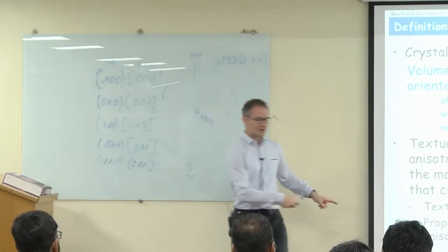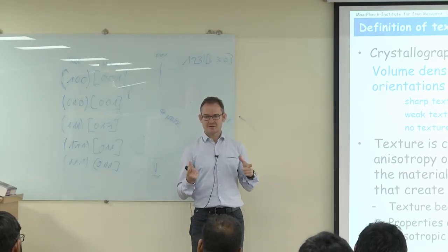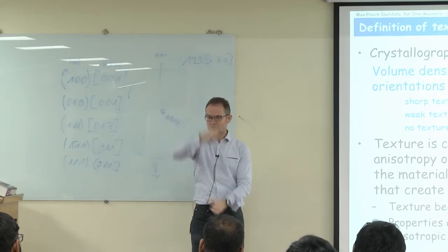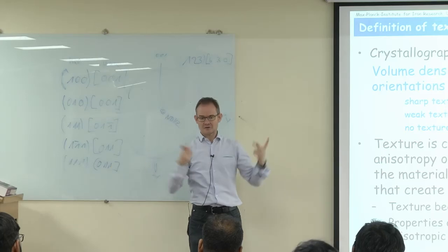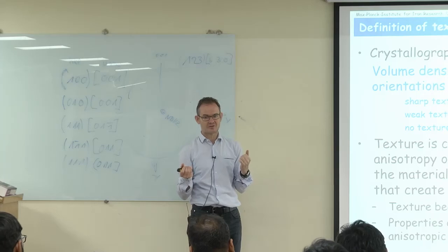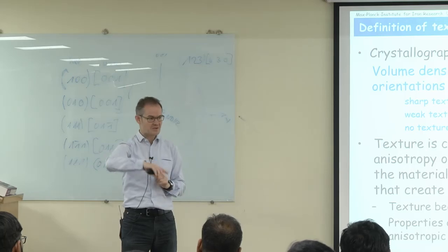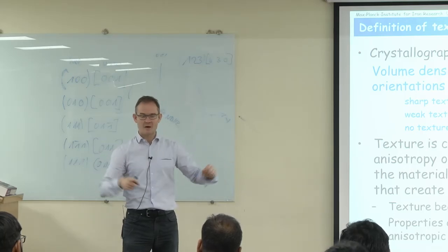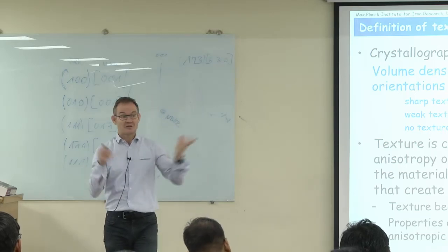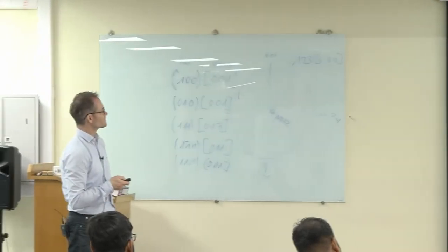And the second thing is, of course, materials have anisotropic properties. A crystal pulled in one direction has a different strength than in the other direction. And if you have a texture, then also your bulk material has different anisotropic properties. And that's what interests us as engineers mostly. Can I have a homogeneous property? In all directions it deforms the same way. In all directions I have the same magnetic or optoelectronic properties. That's why we do all these measurements. So this is clear why we need texture.